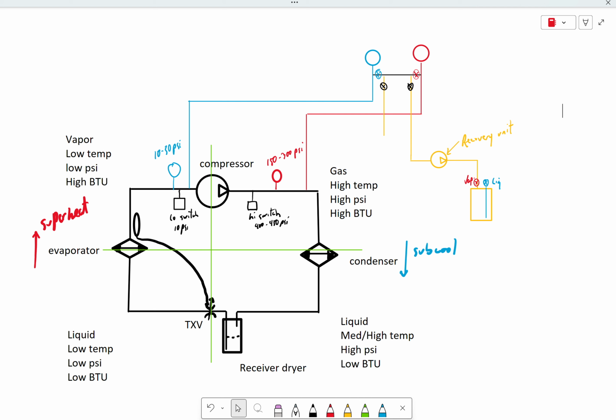So why would we have to do that? Why would refrigerant be contaminated coming out of a closed system? What could have happened? Red Tech. Good old Red Tech. Anybody can go and get their hands on that stuff nowadays, and they can pump it into a system, whether it needs it or not. Cross-contaminate refrigerant, which you're not supposed to do. And then it's your problem, and you don't want to get unlucky enough to cross-contaminate your good tank of 134.